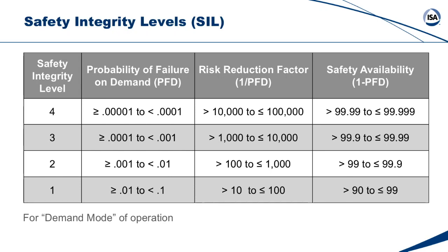But what does it take to design a system to meet SIL 1, SIL 2, SIL 3? That's where money comes in. And that's where fault tolerance and various terms like hardware fault tolerance, safe failure fraction, there's a significant difference in different technologies that will meet all of these different performance requirements.